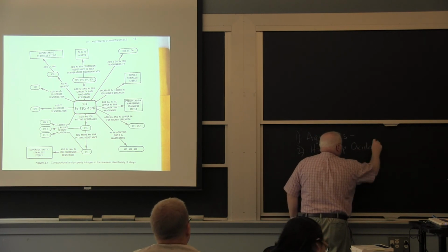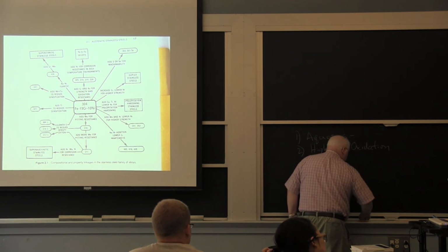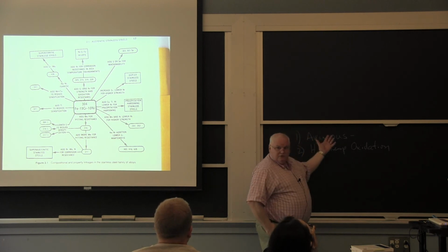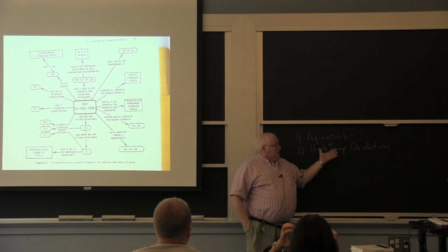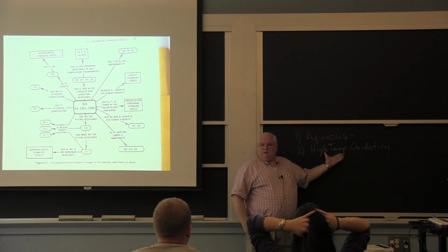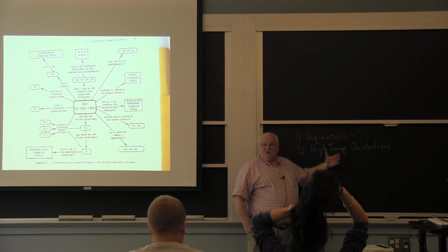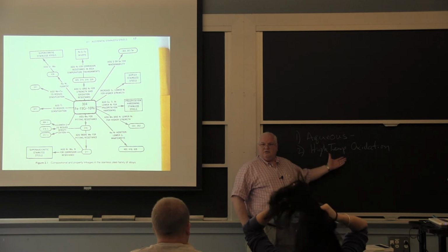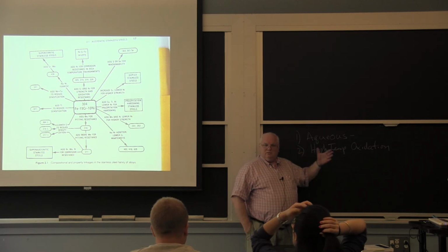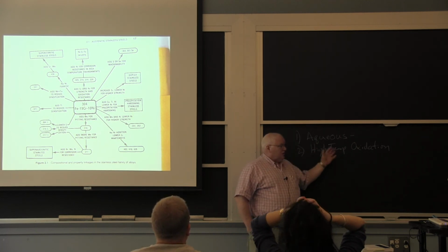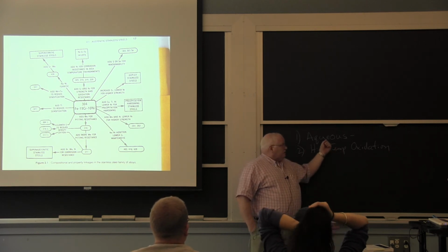And these actually are, in one way they're similar, because it's the chrome oxide on the surface that forms the passive layer. In this case, there's no water around. You're above the melting temperature of water. But it is still the stability of the chrome oxide on the surface that protects you from diffusing oxygen into the steel and forming a big thick layer of rust.